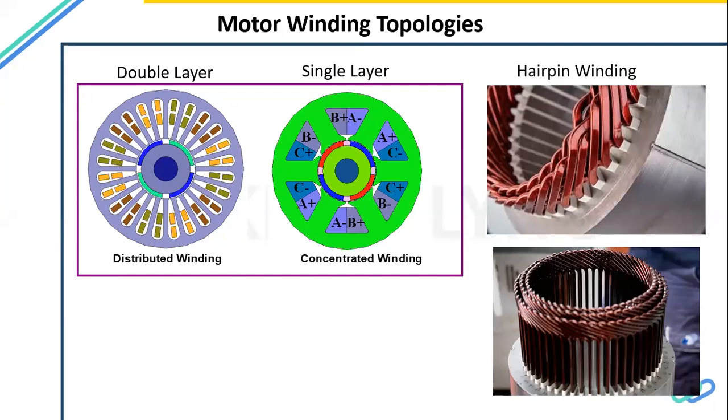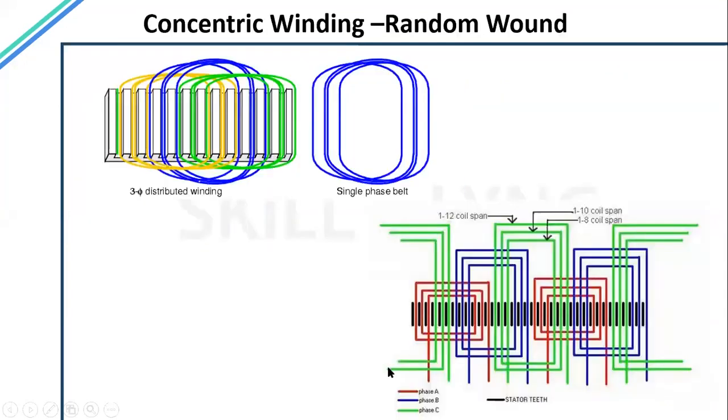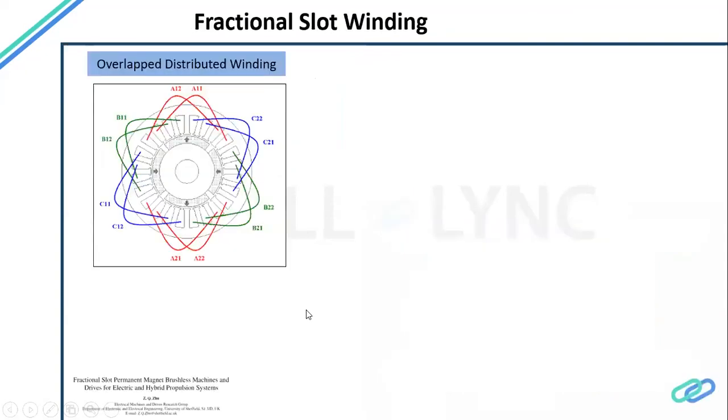We call this a random winding, the usual conventional winding, and this is a hairpin winding. It gives a lot of benefits, but it can be expensive at the same time if we do not have enough volume to handle this. Definitely, if you see this kind of typical conventional winding, they are wound like this. I mean, it is the typical three-phase distribution. You can see here, they are wound like this, having different topologies like this.